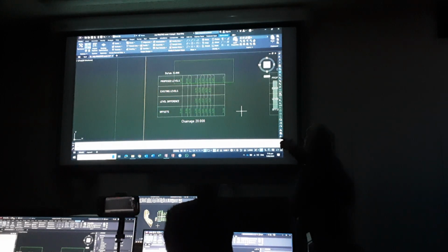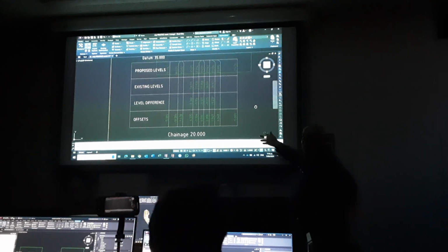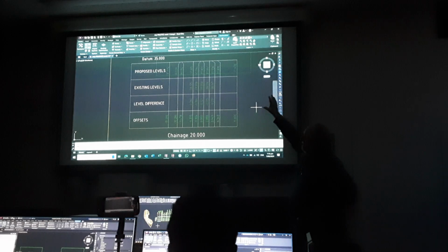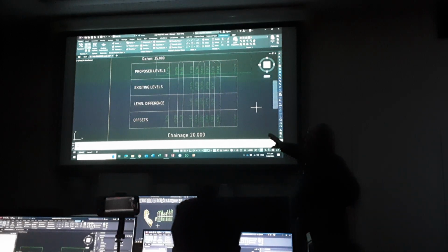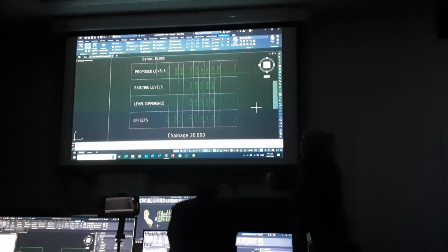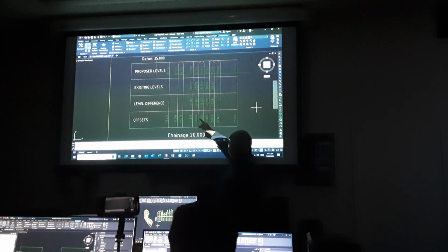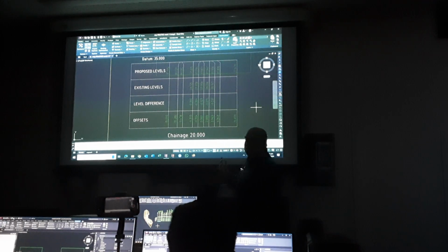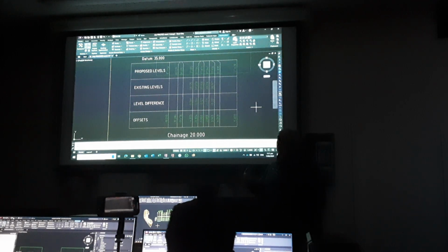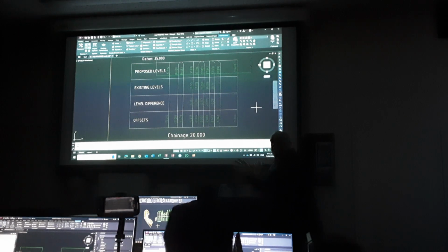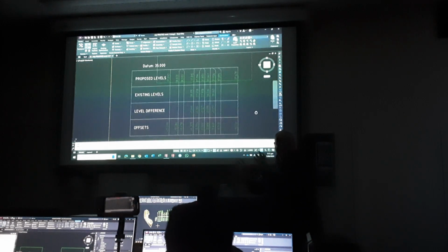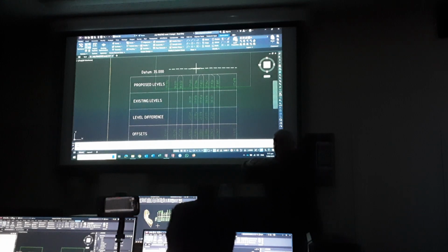What I'm not fine with is you just putting that in AutoCAD and then producing that as your AutoCAD section, because you all know that when you did those sections for me, you had trees and paths on it. If there's no trees, no paths, nothing like that at that section point, then you just need to take out that box and change the level differences to be cut or fill, right? Easy. Where there is a tree, draw it to the right size. And remember, sections are 1 to 1. They're at the exact scale that way and the exact scale that way.